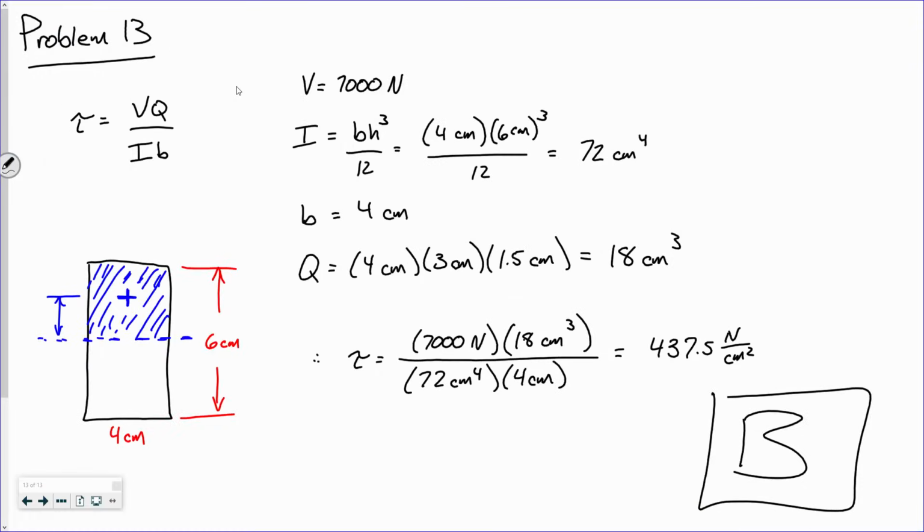So if you go to the manual in the mechanics section on page, give me a second. Say it again. 81. All right. So if you look on page 81, we've got everything related to, oh, maximum shear stresses. This is pretty straightforward. It's just a Mohr circle analysis. Now, the first thing that we're going to do is determine principal stresses, which is as follows.